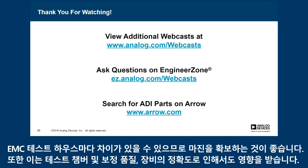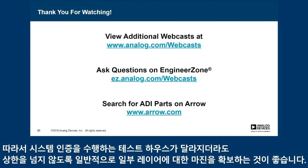It's good to have margin because there can be differences from one EMC test house to another. These are affected by the quality of the test chamber and the calibration, the accuracy of that equipment. So, typically you want to have some layer of margin so that if you move from one house to another in doing your system certification, you won't end up going over the limit.